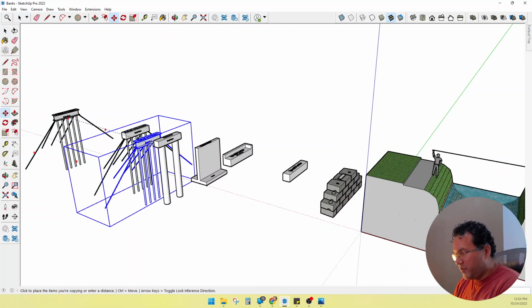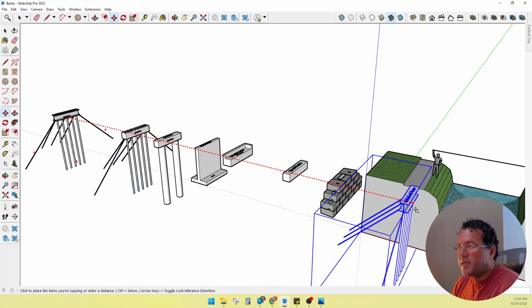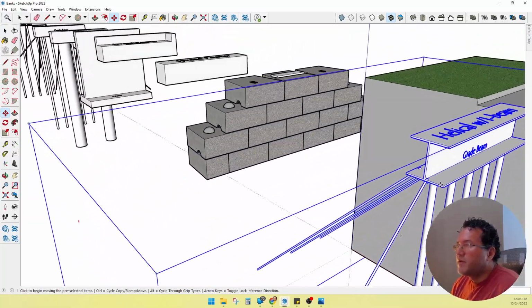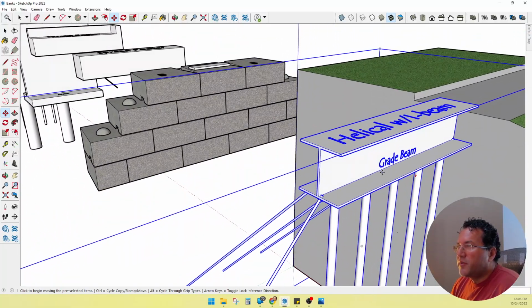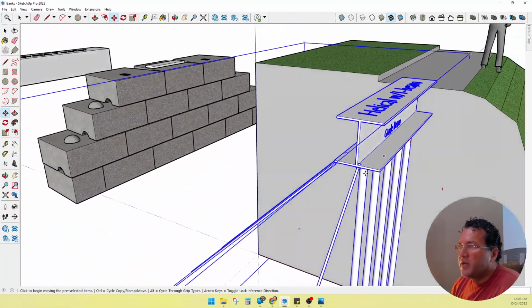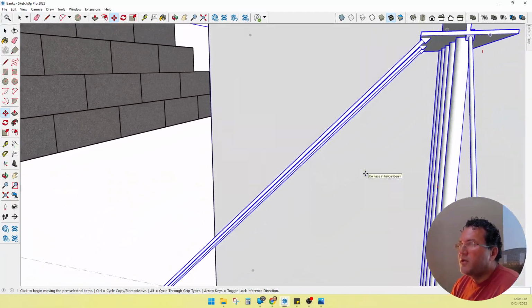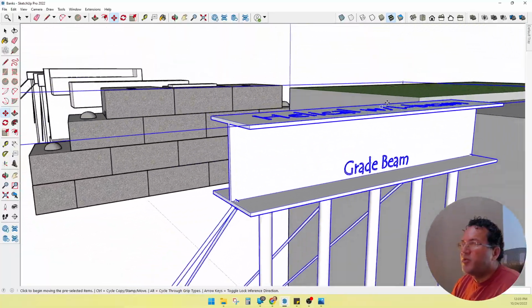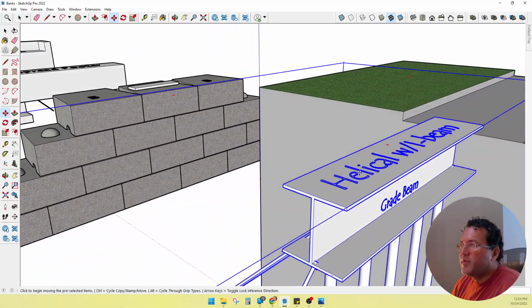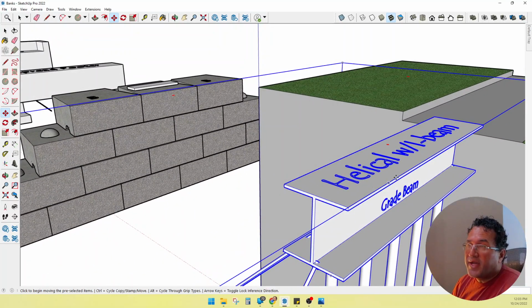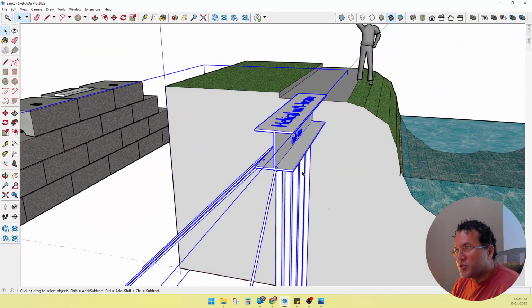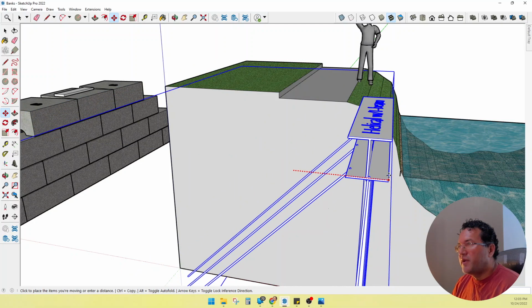Let me pull that one over. It'll look kind of like this, okay? So we'll use a big fat I-beam. This is our grade beam. This is a helical with I-beam. We weld our helical anchors to this I-beam, and then we set our bridge on top of this grade beam. This grade beam is made of an I-beam, and that's how we make that work. This is awesome because we can get super close to this waterway without any concrete whatsoever. Okay, we can get really close.